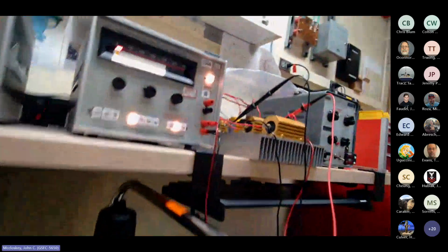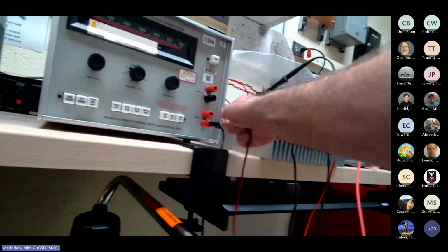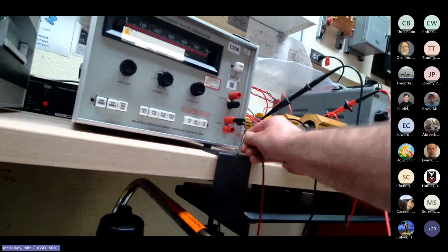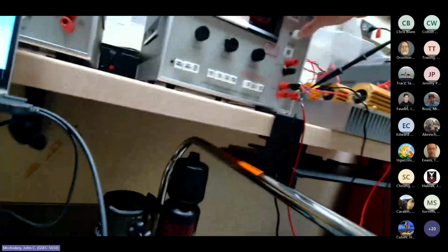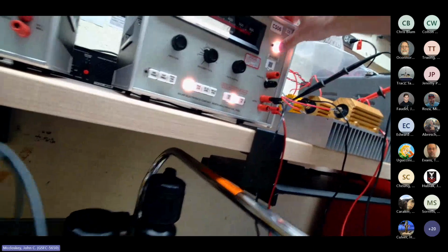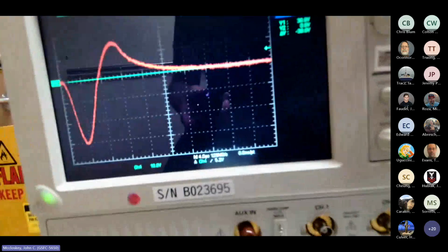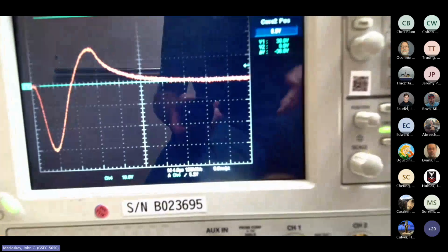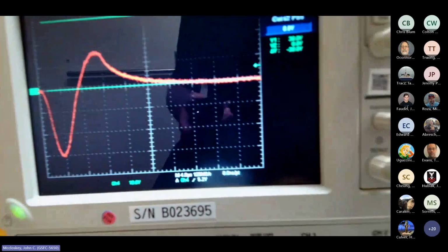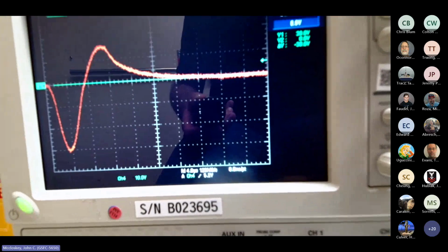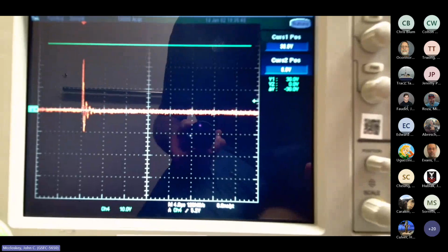But rather than adjust my trigger or any of that stuff, I'm just going to change the connections here. I did turn it off first. So we're still getting a trigger, still triggering on the positive edge, but on this positive edge here. Now let's go to our 150 nanosecond pulse. It's much more compressed now.